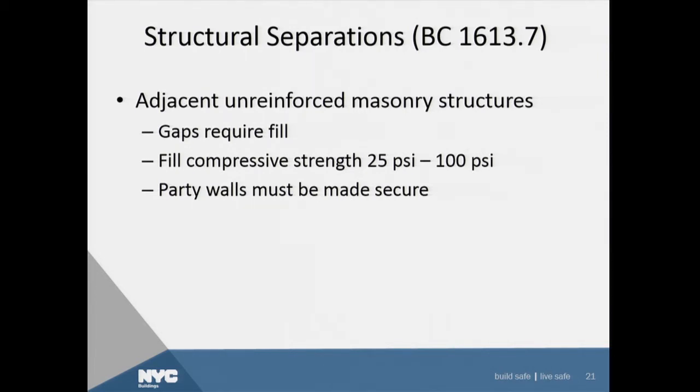But before putting up the new building, you have to plan for what you are going to do with that wall. It is part one owner's and part the other owner's, but that wall needs to be structurally braced. There have been some situations where neither owner intended on laterally bracing that wall, which may mean you have a 6-story unbraced, unreinforced masonry wall in place unless somebody does something about it. The code now clearly points out that the party doing the new construction has to address this.